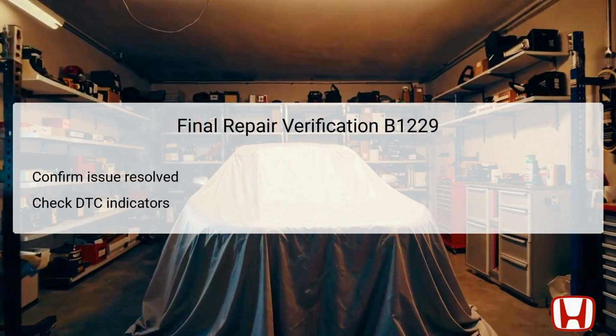The final repair verification step requires that technicians confirm the complete resolution of the issues related to DTC B1229. After repairs or adjustments have been made, conducting thorough diagnostics is crucial to ensure that no DTCs are active. This step verifies that the sunlight sensor circuit is functional and that climate control is responding correctly to changing sunlight conditions.